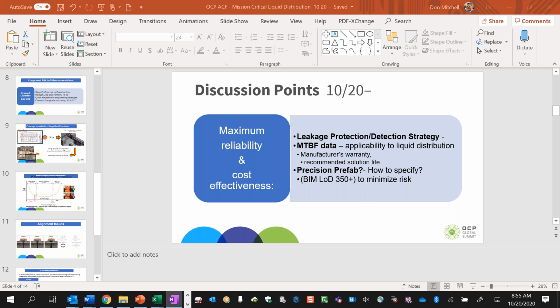So the phrase concurrent maintainability around valves is about comparing a lifespan, or getting a 10-year warranty, versus most valves that I think come by default with a 1-year warranty. You can get them with a 10-year warranty. Is it worth dictating a 10-year one? Well, the gap is back to assembly. The valves may or may not fail because of packing, but you have other issues: flow rates through the piping system, and whether you're going to get turbulence or erosion and cause other difficulties around that valve, because you could identify a packing issue or a leaking valve visually.